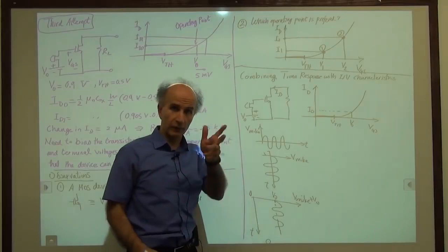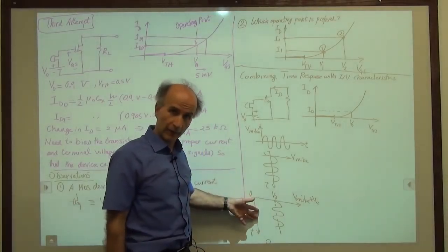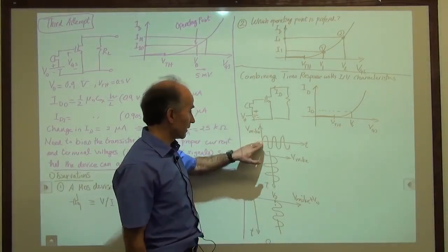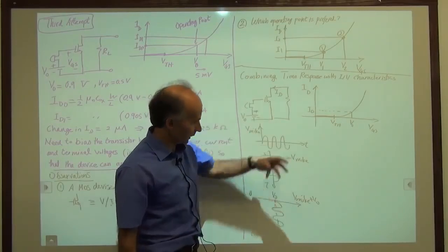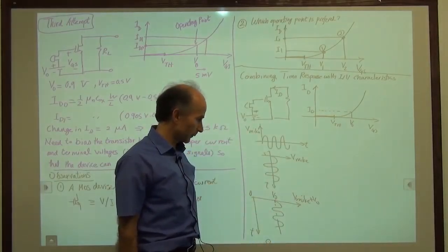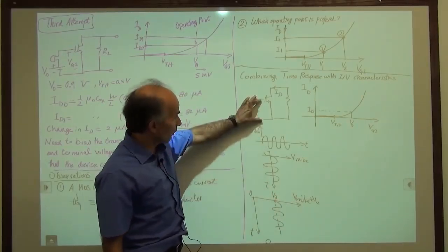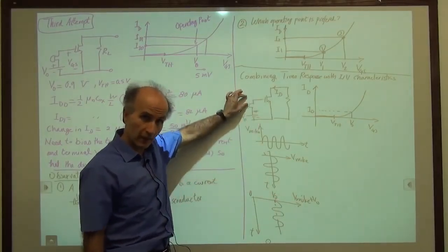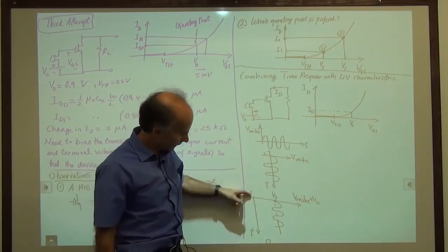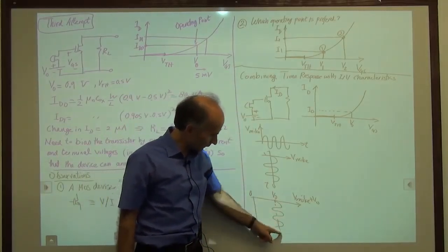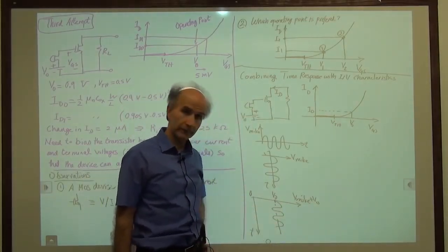That's okay, right? I'm just twisting your mind a little, but that's what we get. You could have drawn this here, shifted this by V0, and then turned by 90 degrees, but that's what we have. All right, so this axis is this whole voltage here, VGS, because it's V mic plus V0. And this axis is time, and this voltage is going up and down around V0.